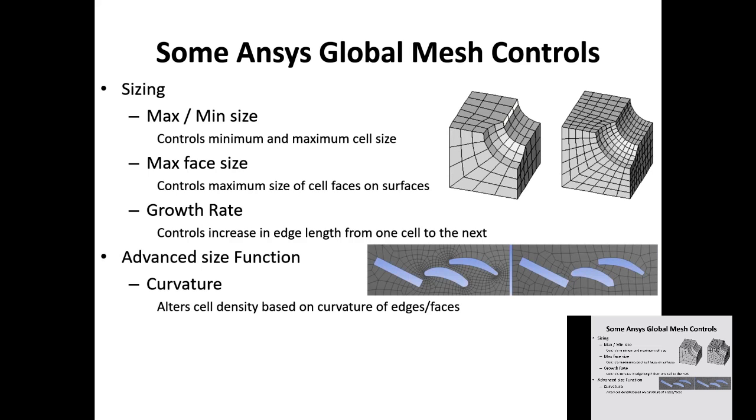And you need to pick up the curvatures well for a good resolution. So for example, if you have an aerofoil like this, you need to have a good resolution in here, because the physics here is fast or acute because of the shape. The directions of the flow change, the vector directions, vector magnitudes all change rapidly here.